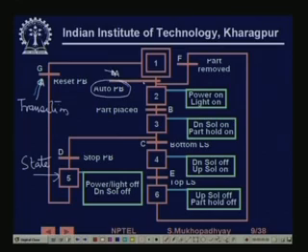Then, if this transition occurs, the system comes to state 2. In state 2, if transition B takes place, whose condition is part placed, it will come to state 3. In this way, depending on how the sensors are bringing in signals from the field, the various transitions will be enabled and the system will hop from state to state. That is the behavior of the system.